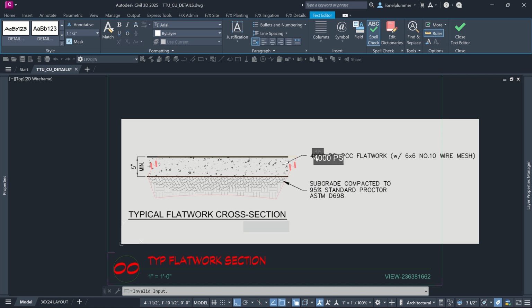4,000 PSI PCC. That means Portland concrete flat work. Now enter, good, it's fine. And then in parentheses, we're gonna spell it out, 6, and now you do make these X's small. 6 by 6, number 10 wire mesh. So that's it.